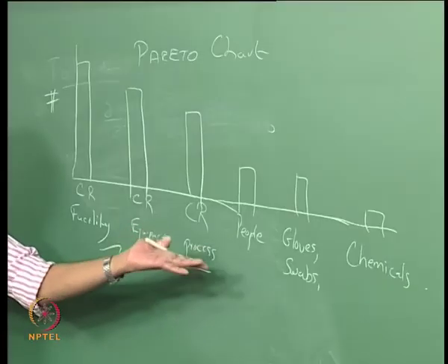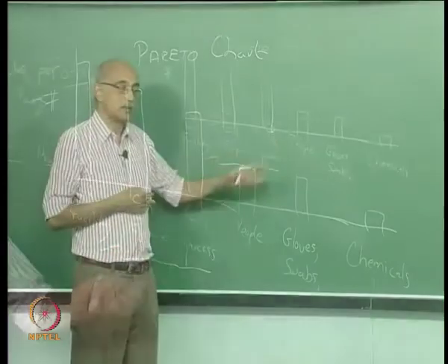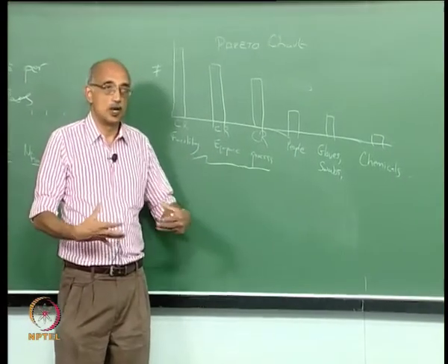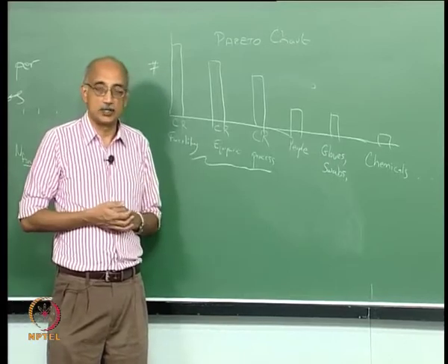People, if you find that people are a major source, maybe they are not wearing the right garments. The primary thing that keeps people from contaminating a clean room is the clean room garment that they wear. So maybe we have to upgrade the level of the clean room garment that they are wearing.